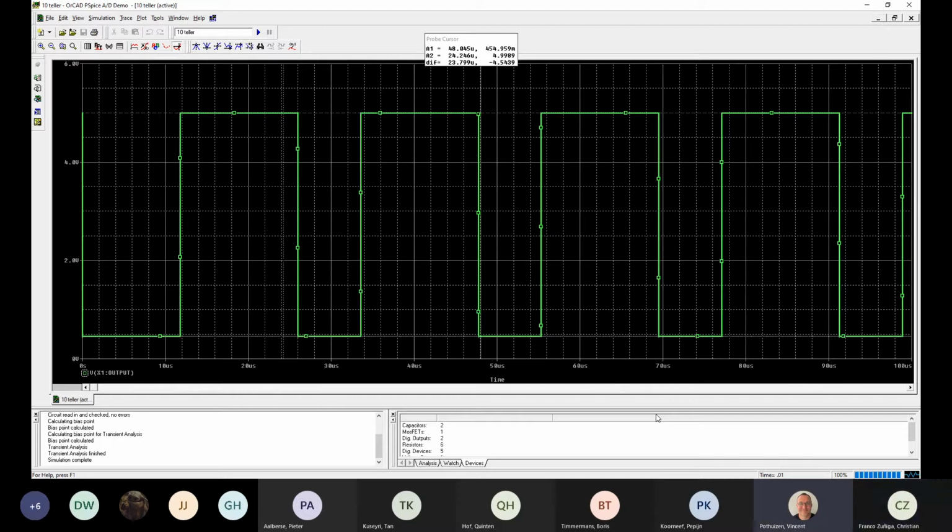This is how you do that for all electronics. If you have an Arduino and you have digital write high and digital write low, and you say it's X amount of time high and X amount of time low. If the time high is the same as the time low, you have what they call a symmetrical duty cycle. Duty means when there is duty, when the voltage is high. What can you say about the duty cycle, what you see right now? Is it symmetrical or asymmetrical?